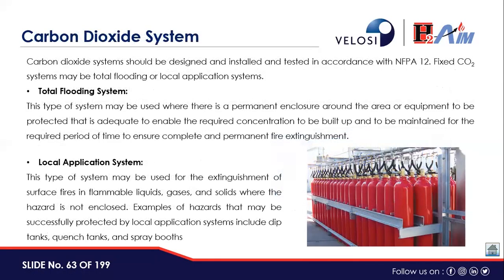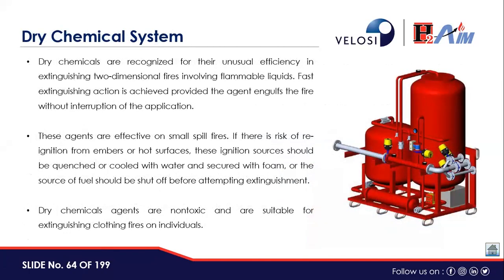Then carbon dioxide is also part of the clean agents as well, but it's a local application or total flooding, and this system is also applied for the control rooms and electrical substations. Dry chemicals we are all familiar with, and they can be placed across emergency sites, and they are more effective when used by humans in the case of small fires.